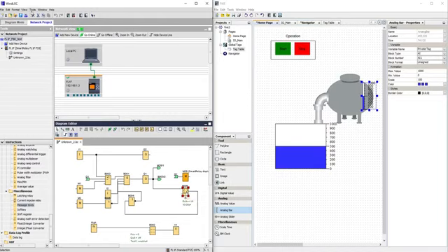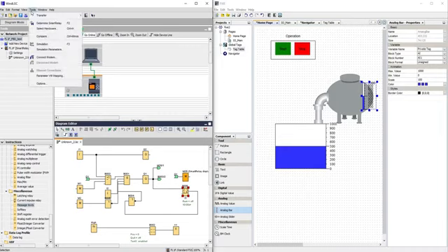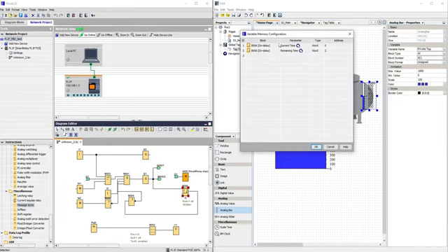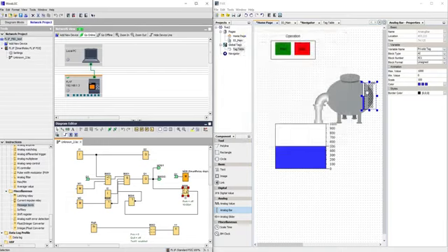So I need to map these two to variable memory or variable register. In WinLGC we have a parameter called VM mapping, where I try to map the current time and the remaining time to variable memory 0 and variable memory 2 respectively, as current and remaining timer. In the web editor here, I'll map the remaining timer to the tank 1 here.